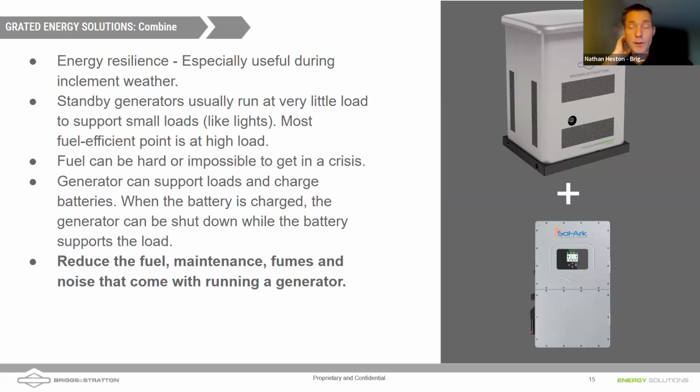Yeah, you could do up to 200 amps on the grid port. So you have that 200 amps of pass-through there. Briggs & Stratton makes the highest power output generator on the market for air-cooled, which is a 26K generator. So it's just a little over 100 amps. I think it's 107, Daniel, for a 26K. Yep. And I put a 125 breaker in there. Yep. And so that could be used on the grid port. If you're not off grid, you'll need a transfer switch to either have the generator on the grid port or have the utility on the grid port.